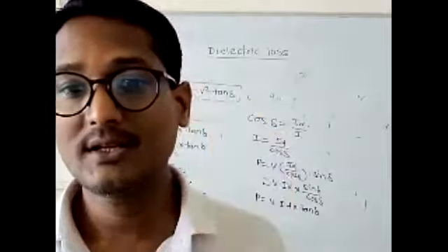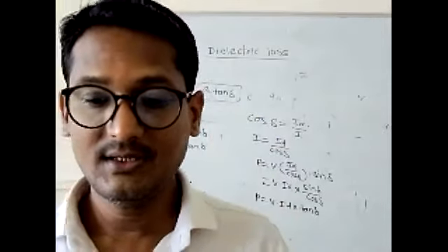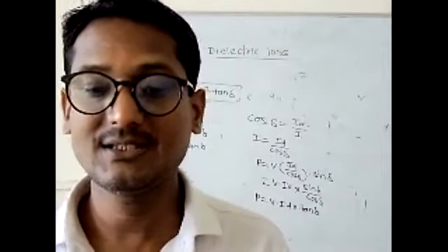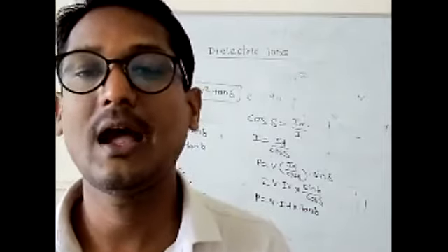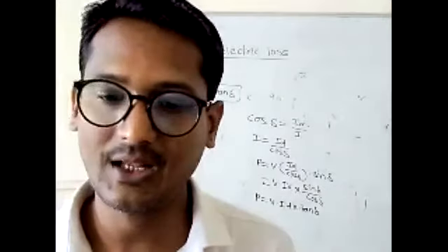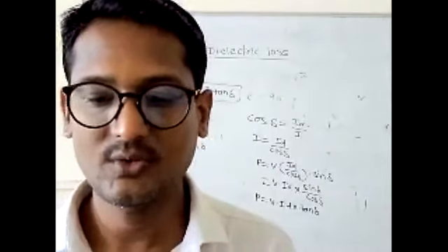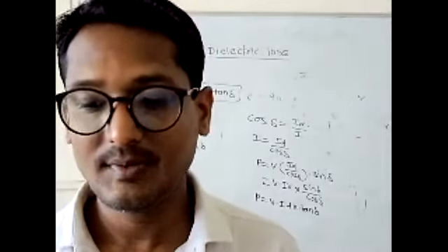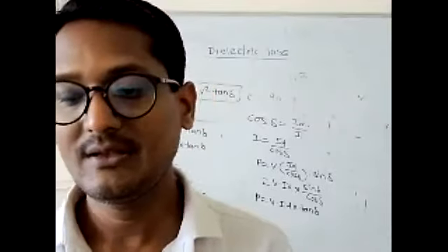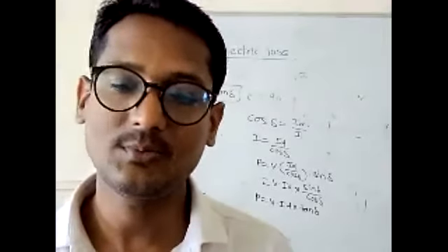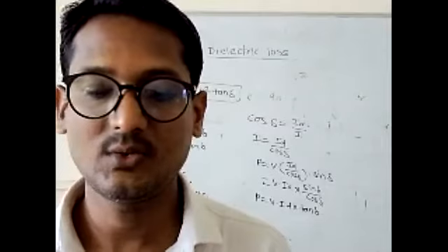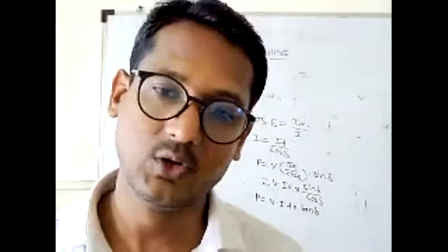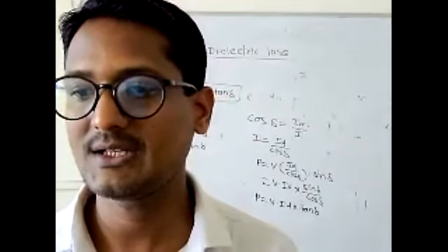That means no current is flowing through that circuit, so it will not absorb any dielectric energy, and hence the resultant current I equals only ID, because the value of IR is 0. For an ideal capacitor, phi is always 90 degrees, so the value of delta is 0. Therefore, the angle delta equal to 90 minus phi is called the dielectric loss angle.